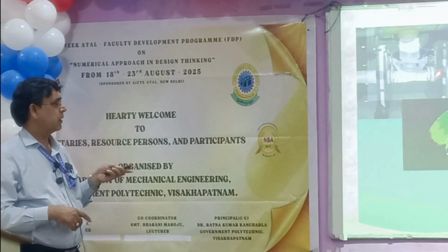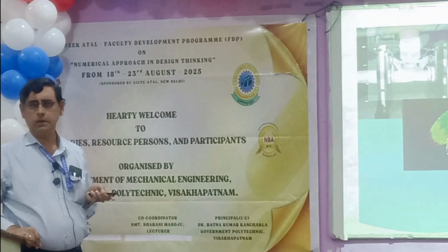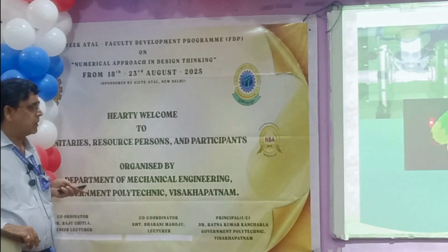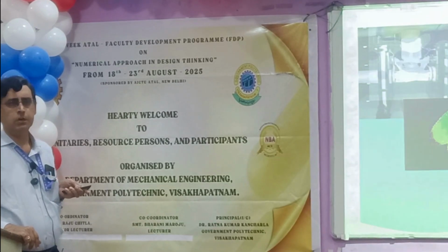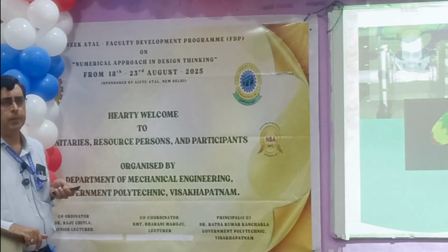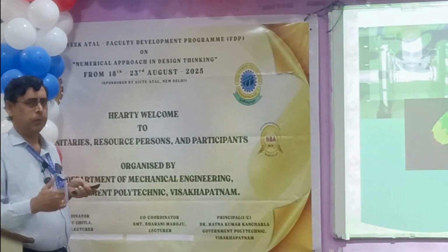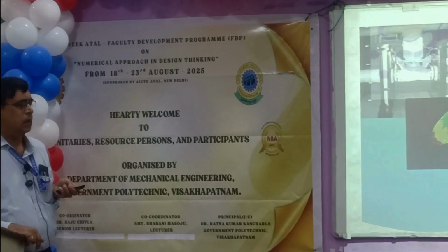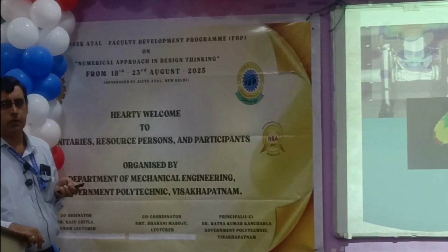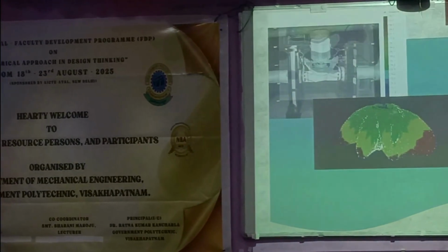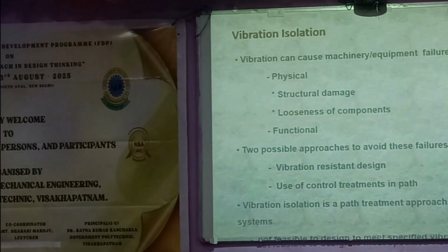Like that you can do for a complete equipment also here, a motor-driven pump, for example. So by that, what you can understand is where the actual source is coming from. It is much easier, because with a 3D map you are able to point out the exact source. So this is called near field holography, acoustic holography, which has become very popular because of the effectiveness of its method.